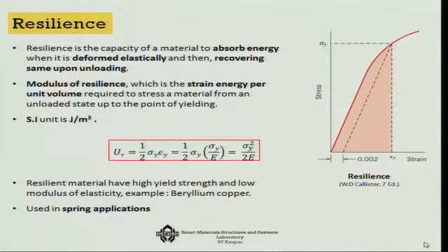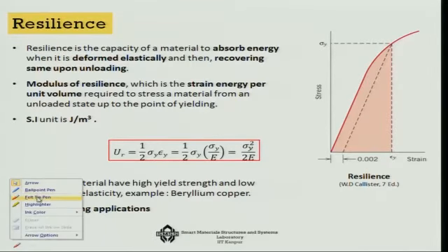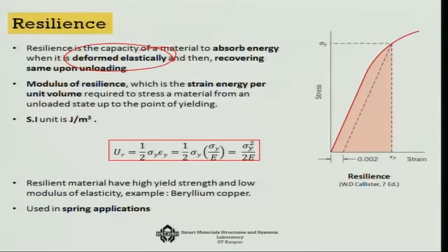Now, the other important point here is actually the resilience of a material, which is the capacity of a material to absorb energy, okay, elastically. So, it is in the elastic domain. When it is deformed elastically, how much energy can you absorb? If you consider the area under the stress strain diagram, you can find that this is something like sigma y square over 2E, as an approximate measure, and that means